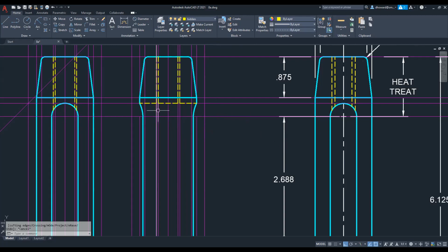We would not show the outline that it would create when one hole intersects another hole. By the way, that shape is known as a yoke. But in the world of drafting, it is not necessary. It's very difficult to figure it out if you're trying to draw it exactly, and it just adds confusion to the whole thing.